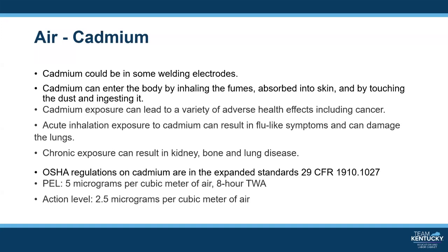OSHA regulations for cadmium are in the expanded standards under 29 CFR 1910.1027. The PEL, or permissible exposure limit, is 5 micrograms per cubic meter of air over an 8-hour time-weighted average.